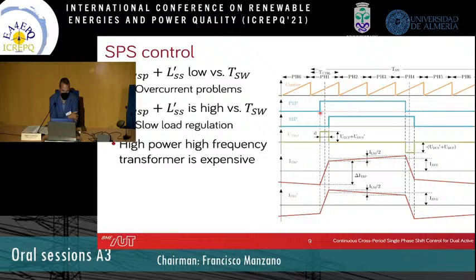The idea is that you provide a square wave or a square signal onto the primary side of the transformer and on the secondary side. And if you provide two square waves, between these two square waves there will be a voltage pulse during this time on the leakage inductance of the transformer, which allows you to change the current which is flowing through the leakage inductance, so what is flowing through from the primary to the secondary side, or in either direction as well.